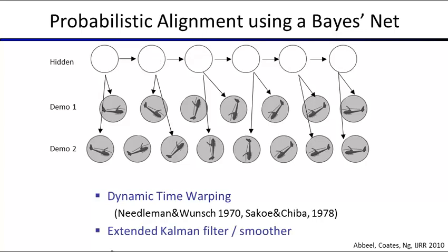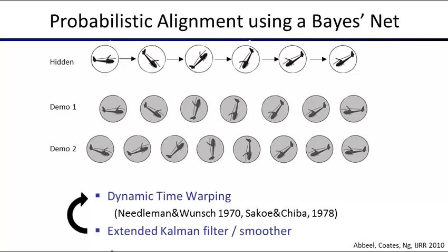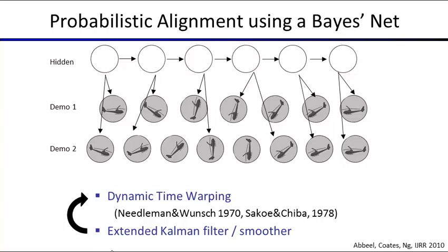You run your inference in your HMM, which, when you replace the summation sign by an integral sign, becomes a Kalman filter. After you did that, you hide the connections. You say, let's now rerun how we should hook things up. Rerun that dynamic time warping. Now hide the denoised trajectory again. Rerun our forward algorithm. You actually also do a backward pass, which is essentially the same as the forward pass. And there is your denoised version of your demonstrations.